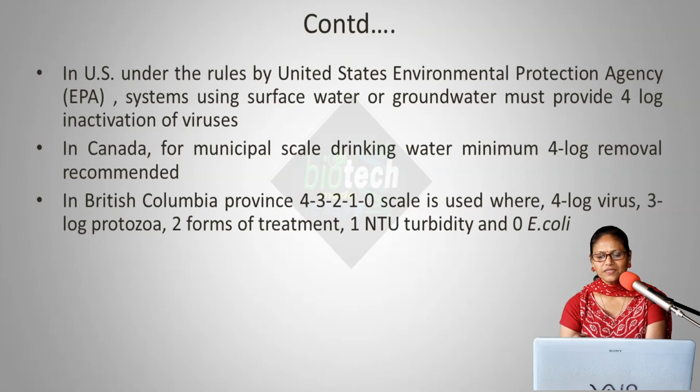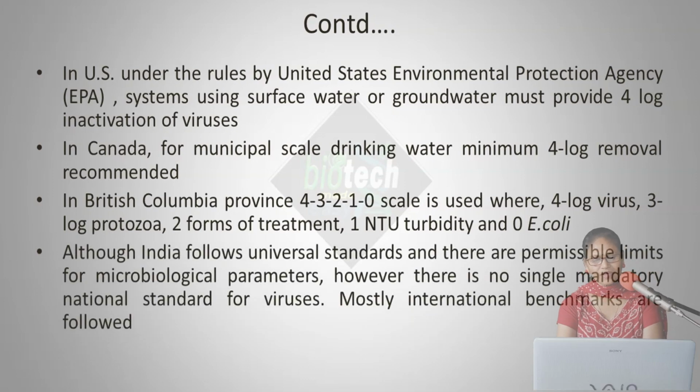1 NTU turbidity. NTU is the unit for turbidity. So 1 NTU should be there as far as turbidity is concerned. And 0 E. coli. E. coli is an indicator bacteria which should be absent in the sample. So that is what is followed in British Columbia.